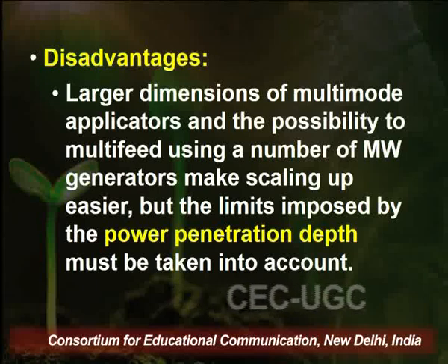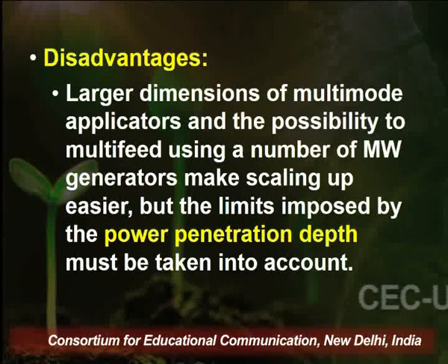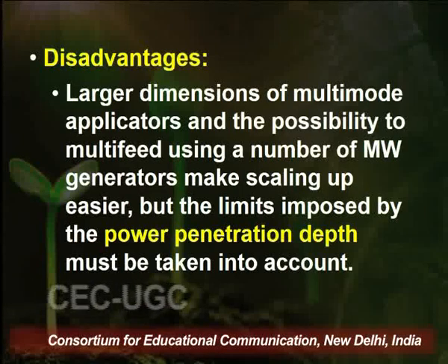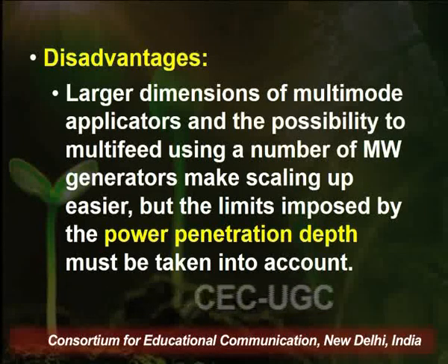This is the major drawback. So one has to be very careful when designing a multimodal cavity of larger size. One has to take care of the power penetration depth of the microwaves. We should not compromise the penetration depth with the increase in the size of the reactor.